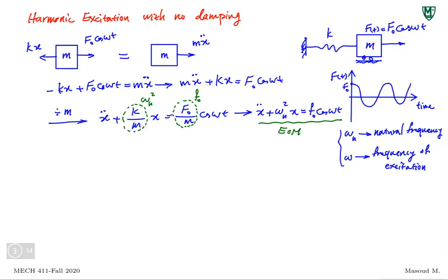So it's a second order differential equation. We saw the left side before. If you look at the original equation of motion, m x double dot plus k x for a spring mass system, the right side was 0, so m x double dot plus k x is equal to 0. Now we have a force on the right side. It's not 0 anymore.